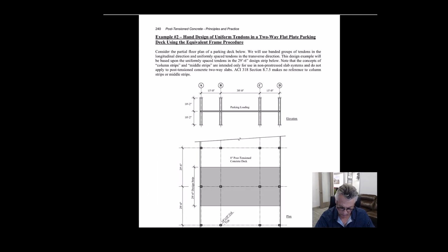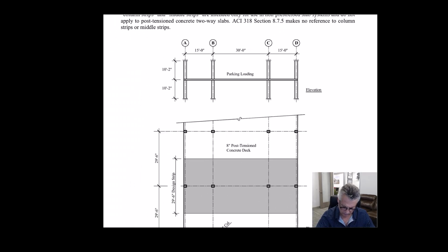What I will tell you, though, is if you go back to this design, we're looking right now at the negative moments here. And I've just done the span to depth ratio on the longer side. But had I done it on the shorter side, you'd actually find that it's the beam equation, the other equation that will control that side.